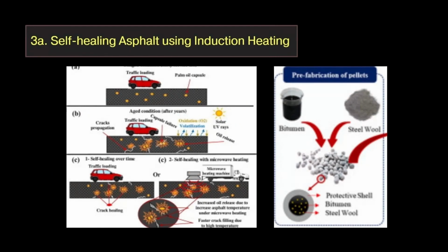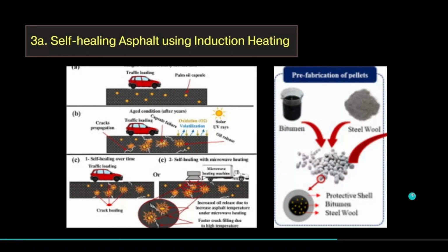Self-healing asphalt using induction heating. Induction heating has regained popularity in asphalt pavement research for improving self-healing in asphalt pavements. Electrically conductive fibers and fillers, for example, carbon fibers, graphite, steel fibers, steel wool, and the conductive polymer polyvinyl, were added into the study of electrical conductivity in asphalt pavement. Results showed that electrical resistivity significantly varied with the type, shape, and size of fibers and fillers. This research was conducted by Wu and Company.